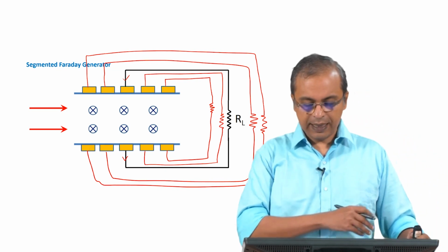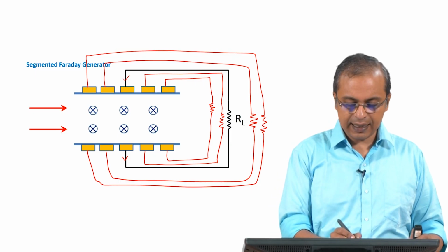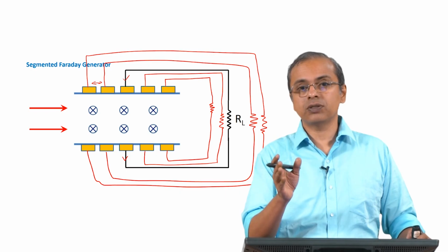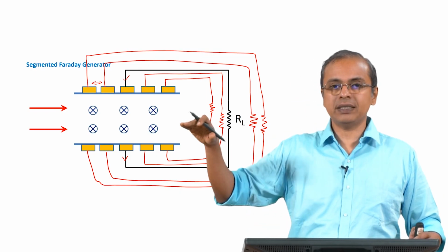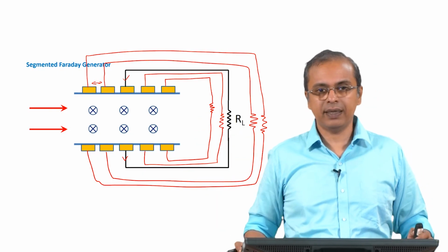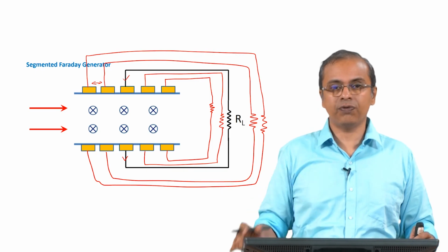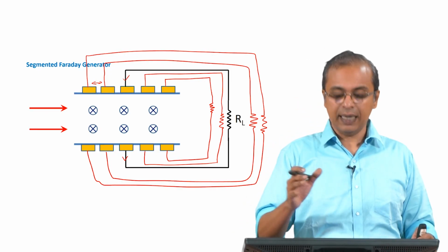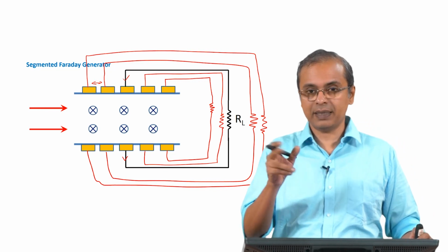Right. So we can pick them up in pairs. Each of them is individually electrically isolated from each other. Therefore it does not force the potential of that entire surface to be the same. If you have a conducting material, it will force the potential to be uniform across that conducting surface. The better the conductor, the more uniform the potential will be. It will be difficult for you to sustain a potential difference across that surface, and therefore you will not be able to capture the differences that may exist from point to point.